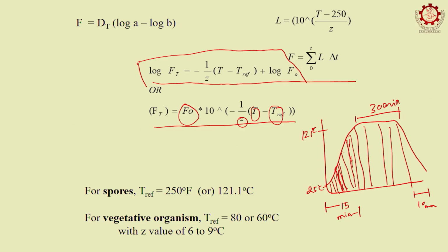So in other words, the death of the bacteria when you are heating and cooling in an industrial environment can happen during the preheating side as well as the cooling side. And then you have to be able to mathematically calculate, using this relationship, what is the total death happening at different stages. However, you don't want to take credit for bacterial death in all those time intervals, because you want to do things much more conservatively, and you can calculate things accordingly.